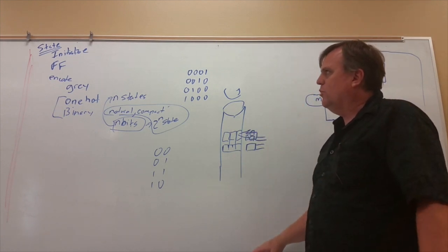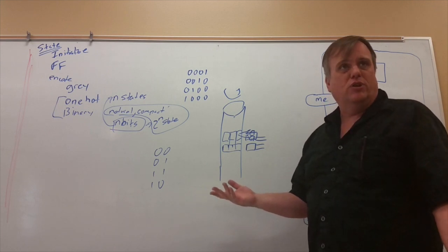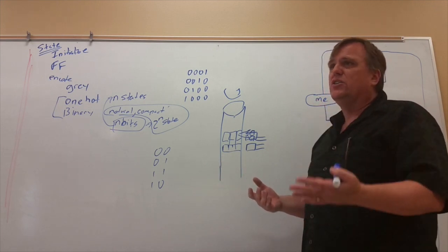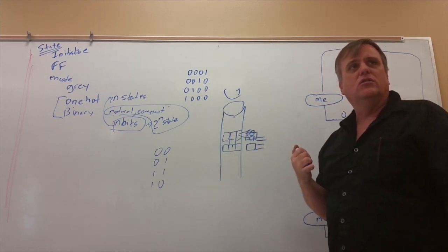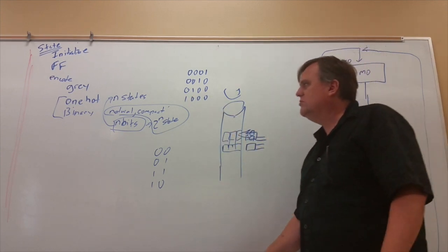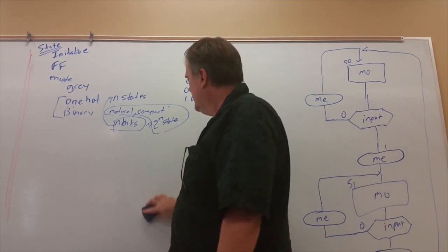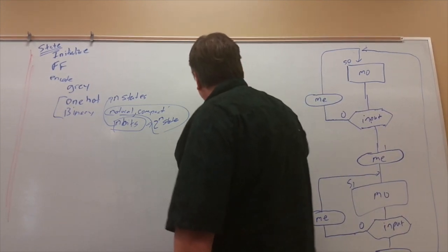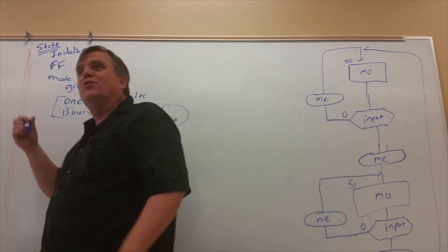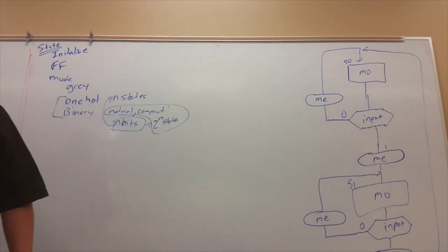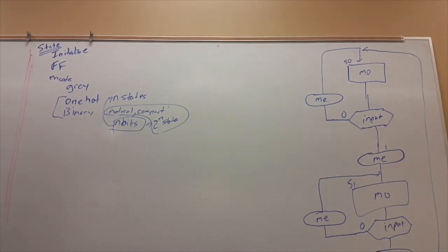These are kind of some standard ones that go in. I've got to figure out an encoding for them. And we'll deal with that in a second. Anybody know, how do I often handle encodings inside Verilog? So typedef is what we get in SystemVerilog. Yes. So that's a nice thing, we get an enumerated type. What we used to have to do is declare local parameters. And so we do a localparam,